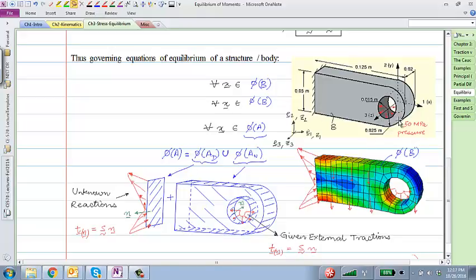In order for a given structure that has some boundary conditions, some loading specified, some material properties, we have not gotten into material properties yet, but we'll do that shortly. So in order to be able to do that, we have to be able to write the conditions that for equilibrium to hold, which are called governing differential equations, GDE: divergence of Cauchy stress plus body force density equal to 0 at every point x in the deformed body phi of B.